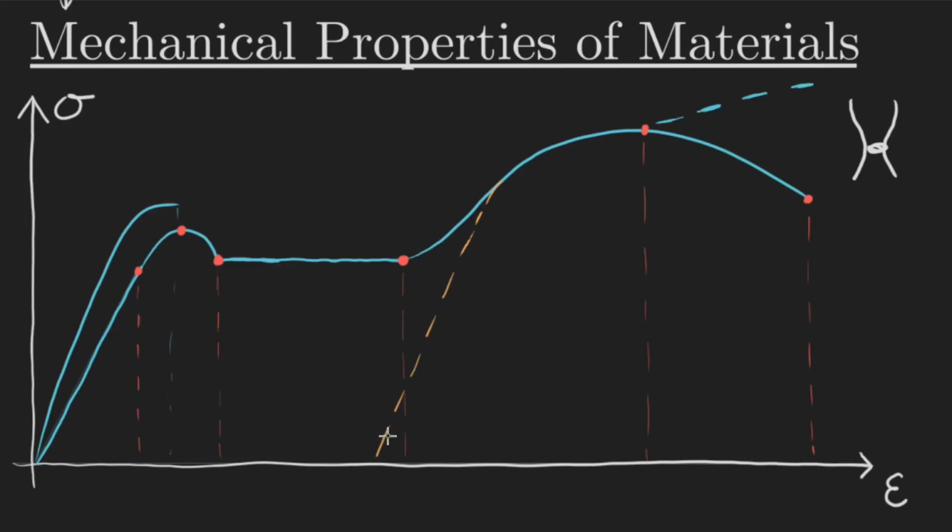So if you have things like cold rolled steel, they'll actually bring it into the strain hardening region in order to get a stronger material. Now, in order to find what stress we call yielding, it's a little bit ambiguous because it just gets longer and longer. It has more strain once we apply this load right here.